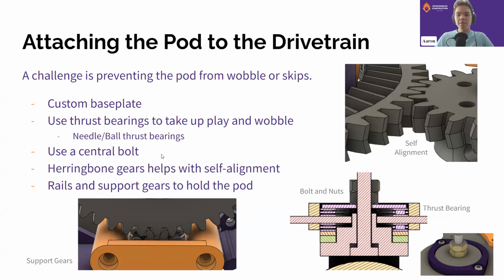Okay, there was another question about using field-centric navigation for this. In terms of the autonomous period, we always have used field-centric, and the actual odometry system that I showed off earlier does use field-centric stuff through finding the angle and modifying it based off of that. In terms of the TeleOp period, we actually attempted to implement field-centric mode for, I believe it was Qual 2, and we found a really interesting problem that comes up with swerve that wouldn't come up with other drivetrains.